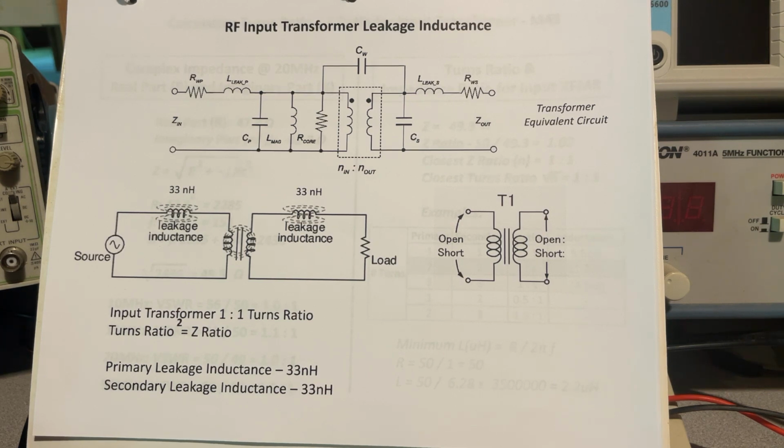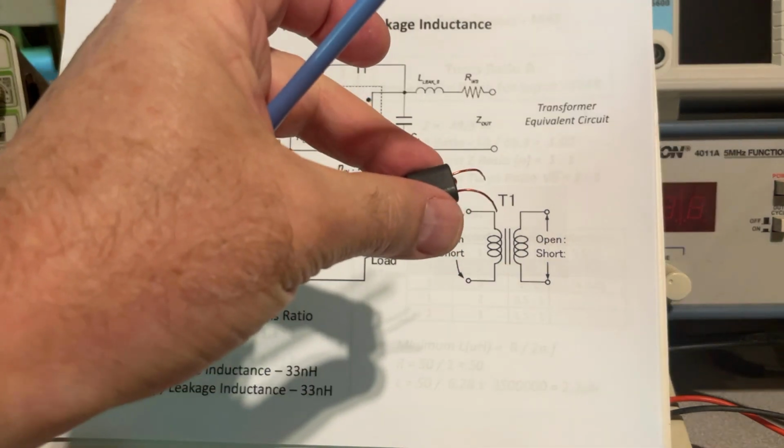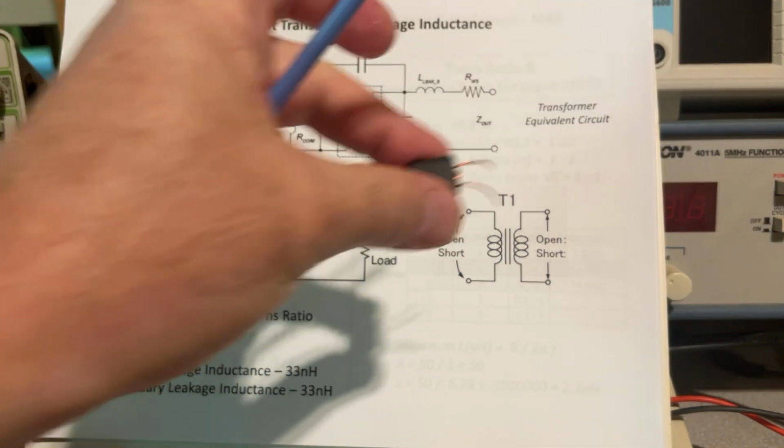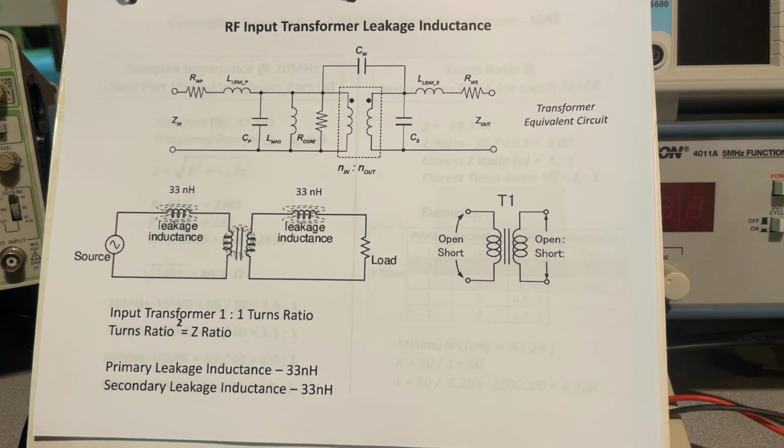Now, no transformer has a coupling coefficient of 1. It's more like 99.99% or 98%, or in this case, this one's 0.9985, 99.85%. So depending on the construction of the transformer, you're going to have more leakage or less leakage, also depending